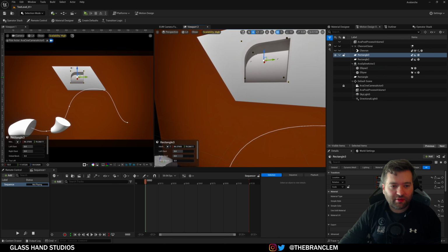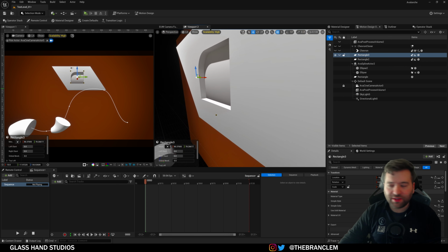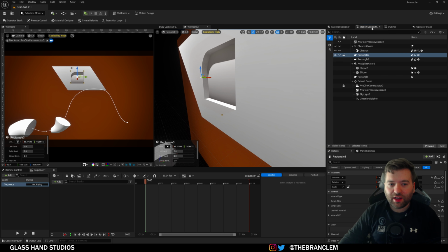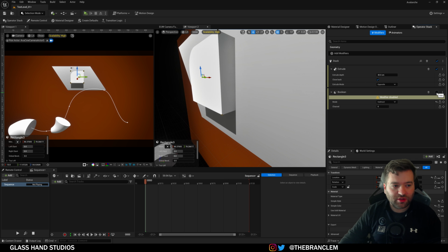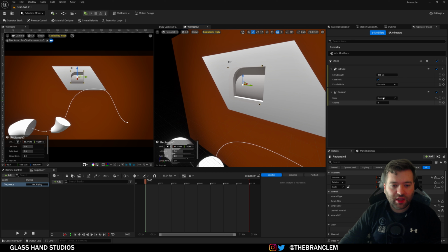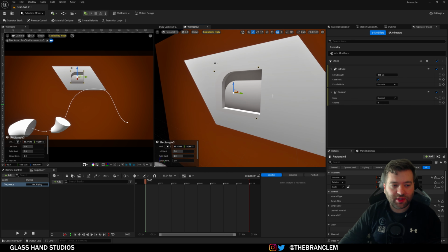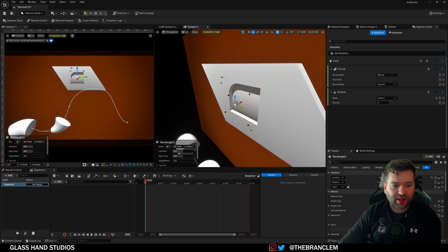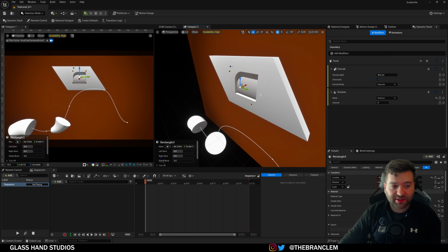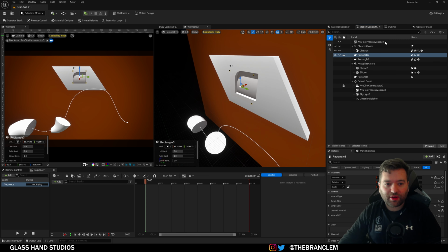And then we also have booleans. I almost said bevels, but booleans. Under the operator stack, we have 2 effects. So we can do an extrude effect. Once we extrude it, then we can cut it into the shape. This is set to subtract from the target, and then you can see once I clicked on the background rectangle, this is set to target channel 0, which allows me to just specifically target this guy. And of course this is completely dynamic and it works in real time. It's amazing that we can do these kind of shapes and cut them out.